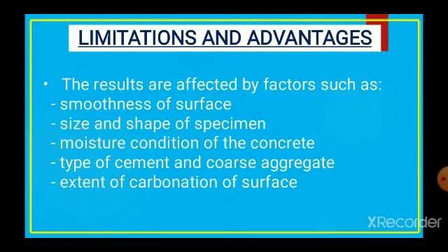I am John Paul Tayaban from BSc1 ICE2, reporting on the pull-out test on concrete. First, I want to read the meaning of pull-out test on concrete. A pull-out test measures with a special ram the force required to pull from the concrete a specially shaped steel rod whose enlarged end has been cast into the concrete to a depth of 3 inches or 7.6 centimeters.